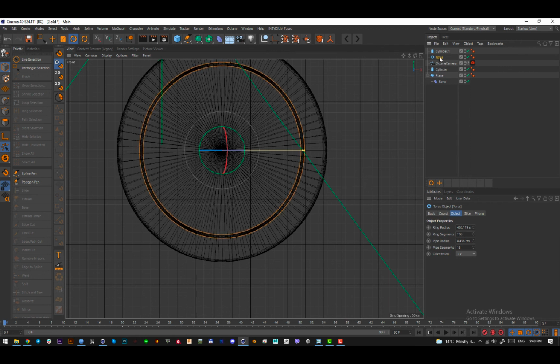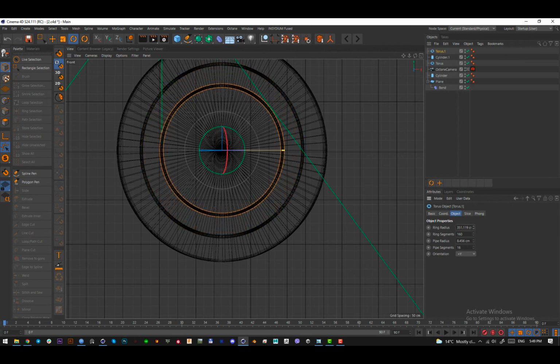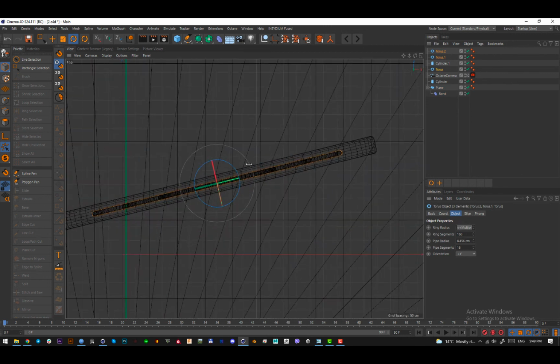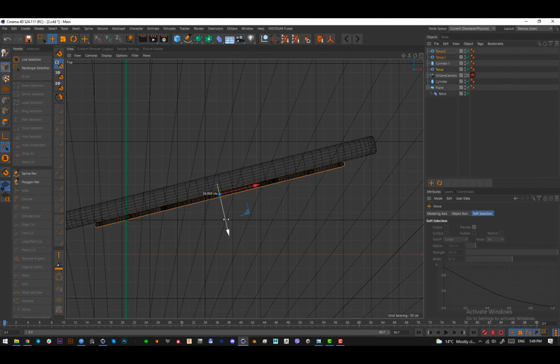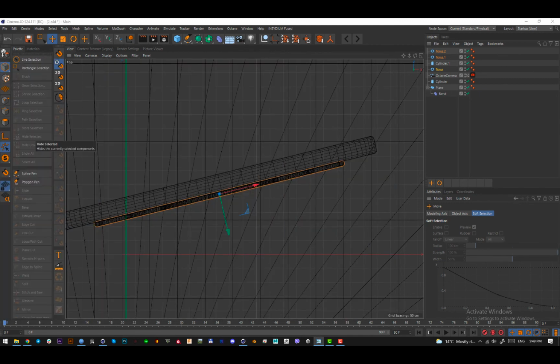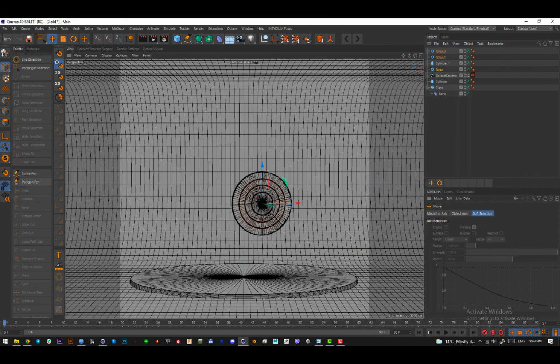Now you should copy the cylinder, so Control C, Control V, and now decrease the ring radius. Okay, and now Control C, Control V for this cylinder and decrease this ring radius as well. So this is what we get. Hopefully we can select all 3 cylinders, jump into the top view using F2 and just pull them out like this so that we can see them. Okay, here they are. This is our first element.